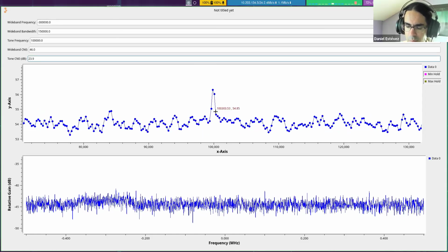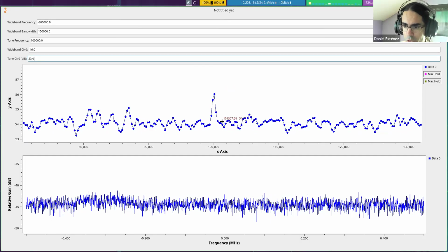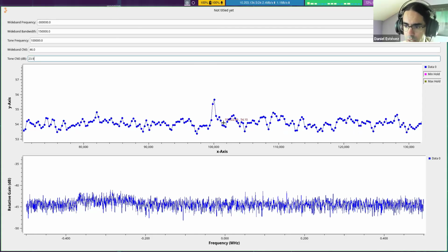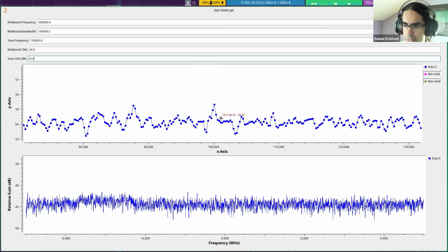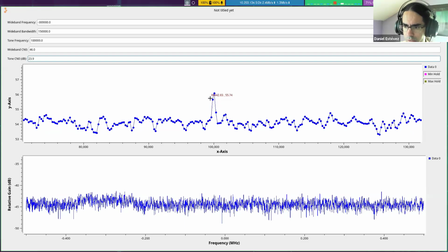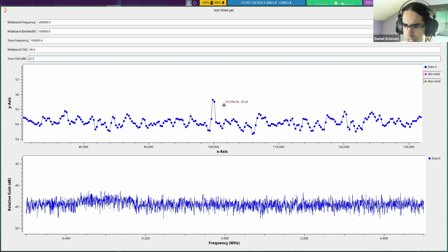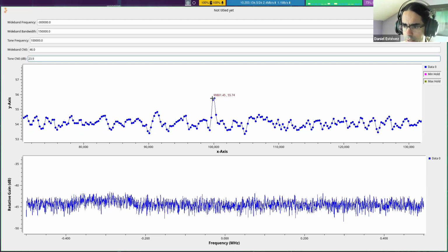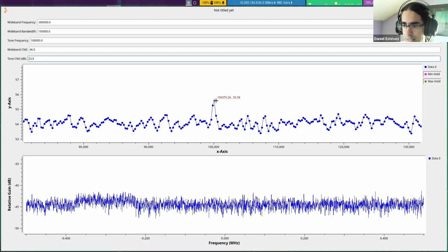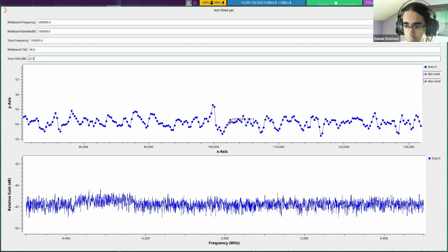If it has about the same power or more power than one noise bin, we will be able to see it, because the signal itself is concentrated on about one or two FFT bins. Next, we will see exactly what determines that. And if it has a power which is comparable to the noise power in those bins, we will be able to see it.